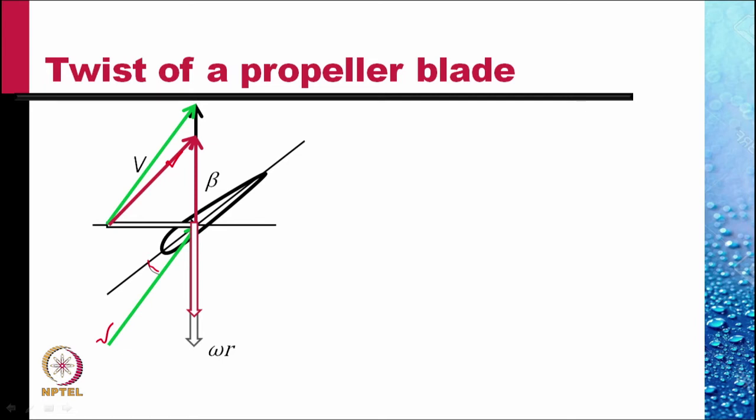And so when we transfer it to the blade, this is what the relative velocity is. And you see clearly the effective angle of attack has decreased. So the blade would act differently than it was acting at that R.